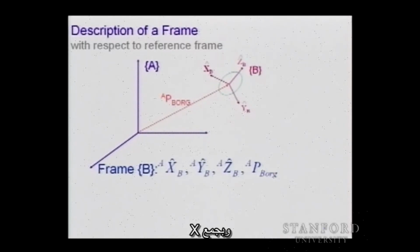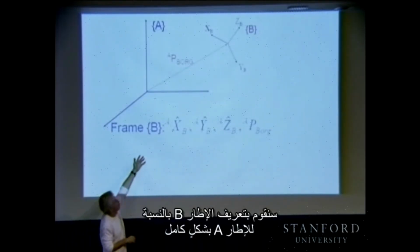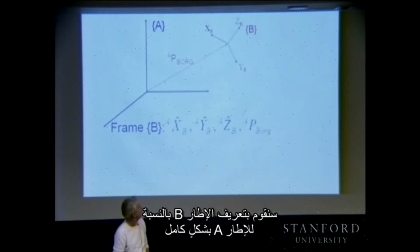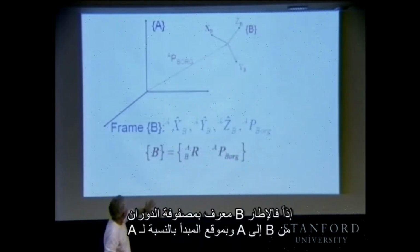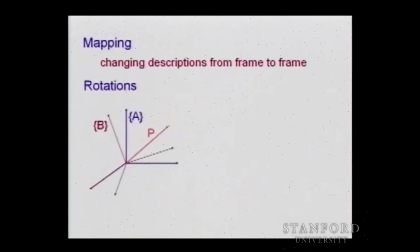And by combining the description of the rotation, those vectors, and by locating the origin of the frame B with respect to A, we are going to define fully the frame B with respect to frame A. So the frame B is essentially defined by this rotation matrix B to A and by the location of the origin with respect to A.